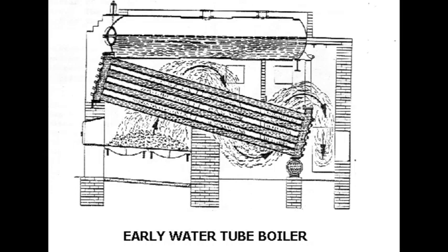Though there is no choking hazard due to soot inside the tubes, as water is flowing through the tubes and heating is done outside the tube, there is no large shell requirement to hold the water, and in this type of arrangement large capacity steaming is possible without any difficulty in manufacturing, and it is also found to be safer.